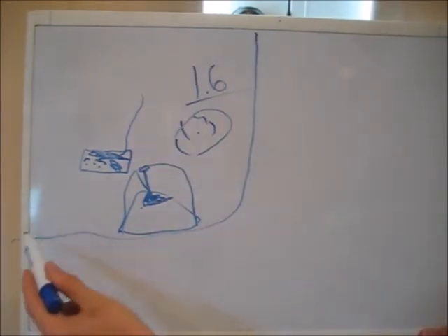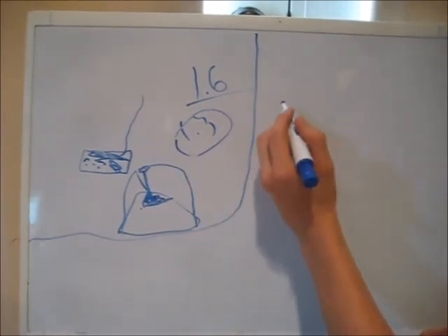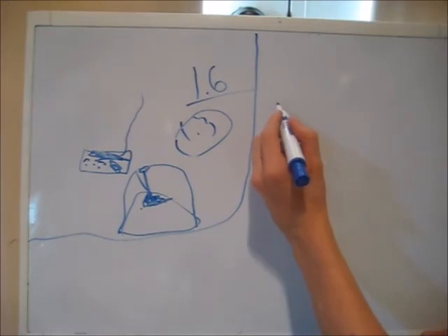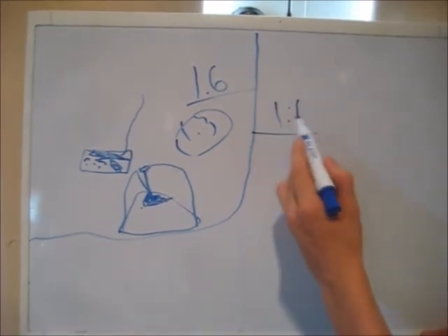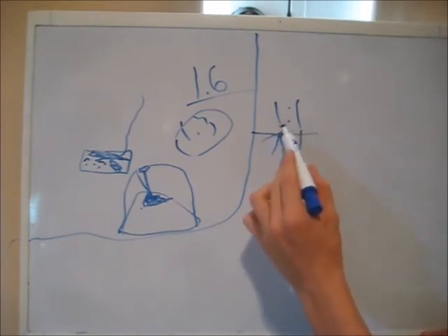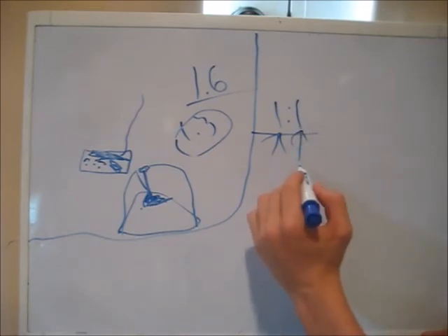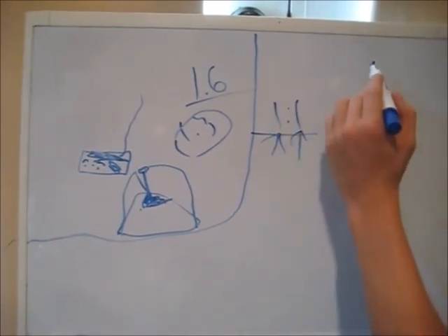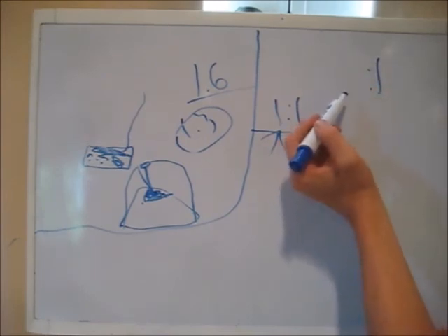What is SWR? SWR is a ratio, standing wave ratio. Standing wave is just reflected wattage. So a 1:1 SWR is 50 ohms to 50 ohms. This number represents the ohms of your antenna, and this number represents the ohms of your radio. That is why this number is always 1. 50 ohms is considered 1. On this side of the ratio, you have more numbers.